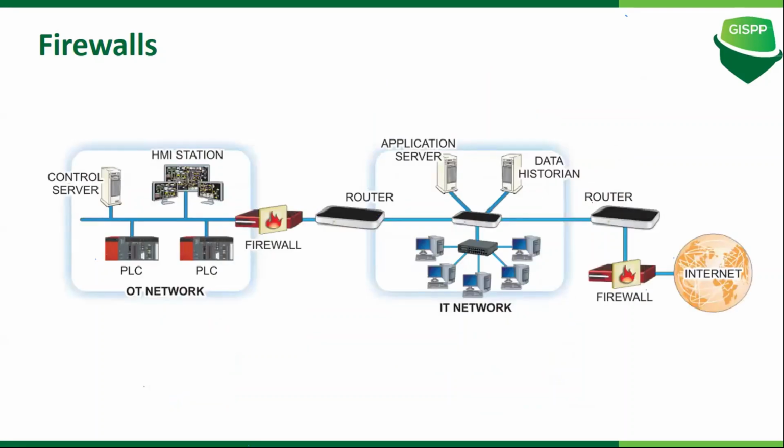We can build another boundary protection by introducing, from the IT network, a router, and from the OT network we can build a firewall, so that the firewall and router connect to each other, and then it can go to the IT network's router, which goes to its switch, and then we can place some part of the OT network like the data historian there.